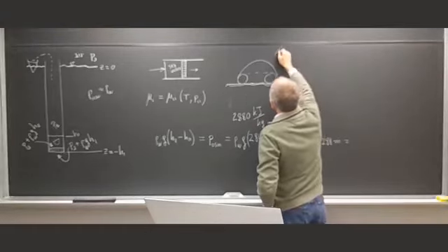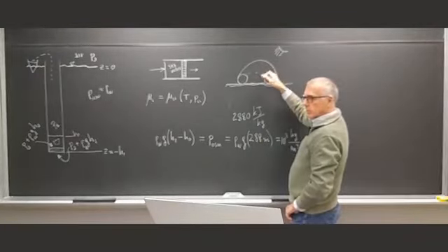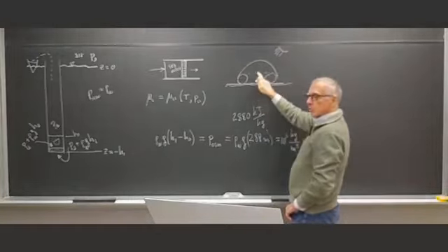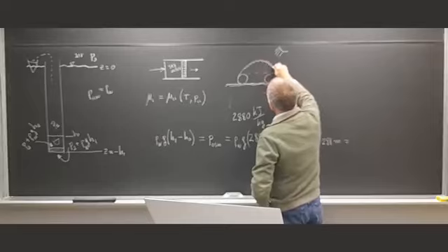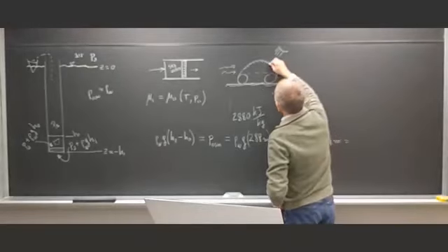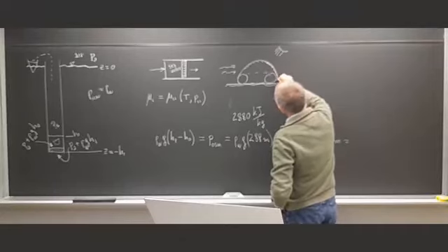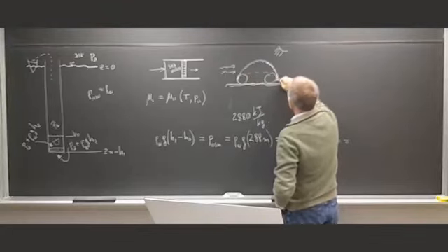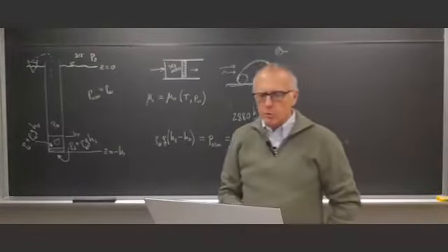So you get sunlight coming in, which makes some of the water inside evaporate, like in a greenhouse. The water vapor that evaporates, the salt remains here, so what evaporates is just water. So the water vapor condenses on the dome, because you also typically have some breeze or wind that will cool that dome. And then the drops by capillarity stay and get collected on this side here. So eventually you get some water on this side, and you put a little pipe and a little bottle, and you collect your water. So that's a survival kit for the fishermen.